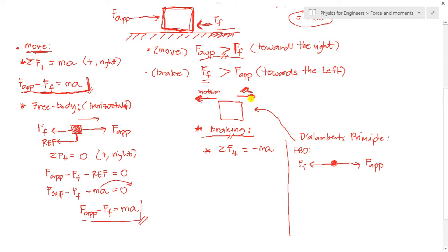So where is the direction of our reverse effective force? It is toward the right, since we applied the brake. Just remember that when you brake, you are thrown forward. So therefore, our reverse effective force here is towards the right. So that is our REF.